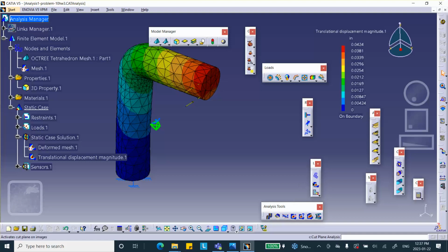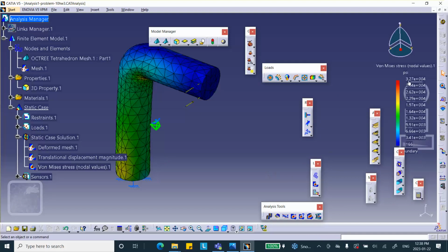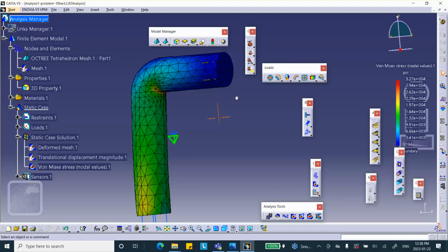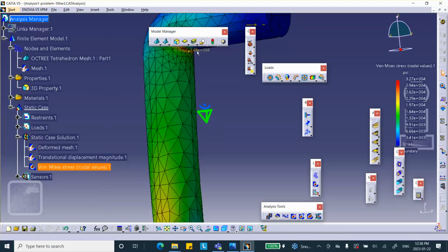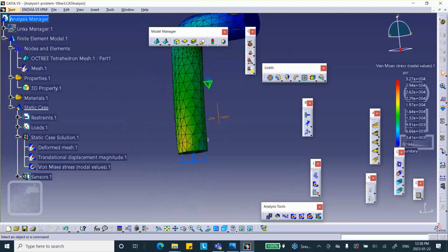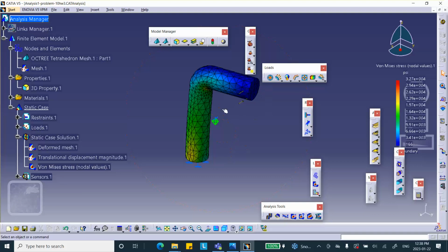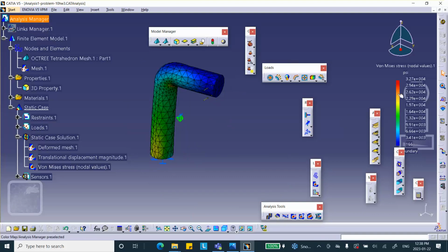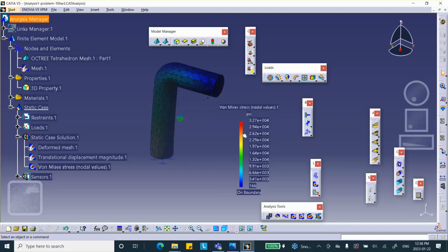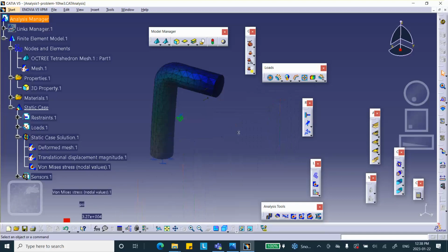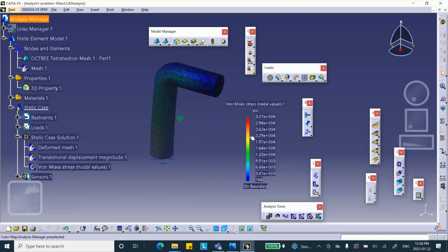Now look at the von Mises stress over there. We are not assessing accuracy here because notice that the regions of big stresses are either here or there depending on the relative sizes of these two pieces. Incidentally, let me select my legend. You bring it here. When you're done, you deselect it. Now, the reason that you may want to move this thing is because you can zoom in and out, select it again, use the usual zoom in and out. You can move it around. When you're done, click on it.